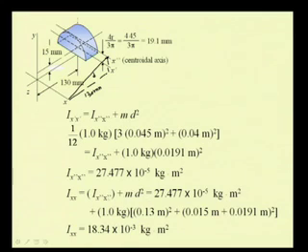So, we have this as 27.477 into 10 to the power of minus 5 kg meter square, and which is the quantity, that is 1 kg, the mass of the element, times 0.13 meter square, this 130 mm, plus this distance, that is 0.015 plus 19.1 mm or 0.0191 whole square.